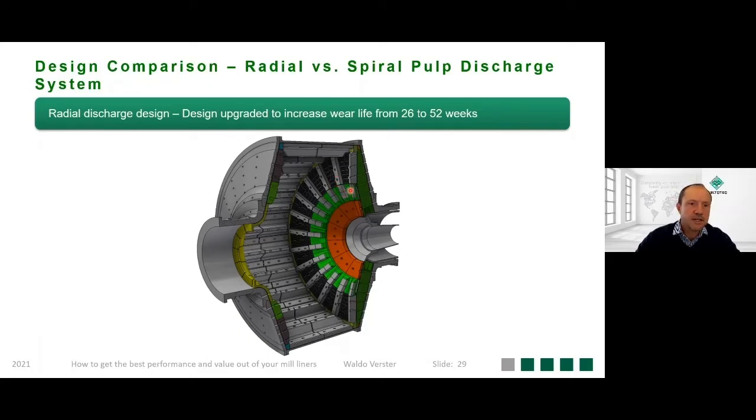Moving towards the inside, we have an integrated liner where we have integrated the lifters into the head plate. And this is based on the heavy-duty Multomed design, where we used chrome moly inserts to counter the high wear areas. On the inside, we have a protection liner. And then outside the Multotec scope, we've got the central discharger in this position.